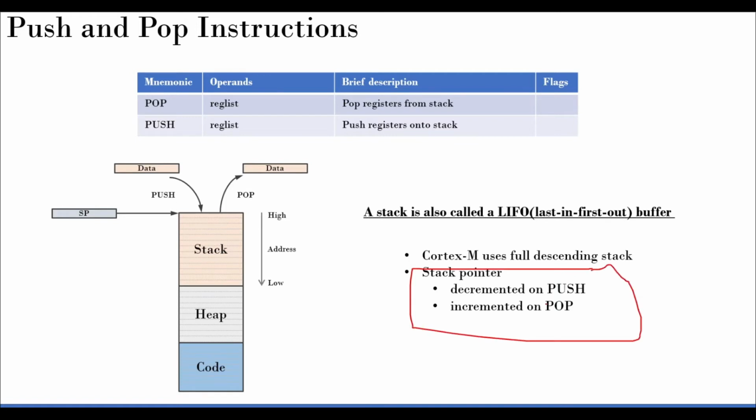A very important point is exactly written here. This is against the convention, because typically when you add data to memory you increment the address of the memory. That's very common, that's what we did in our 8-bit microcomputer also. But in the case of the stack, since it's a last-in-first-out approach and it grows down, whenever you add content to the stack, the stack pointer is going to get decremented. That's the interesting aspect, because you're going to start from here.